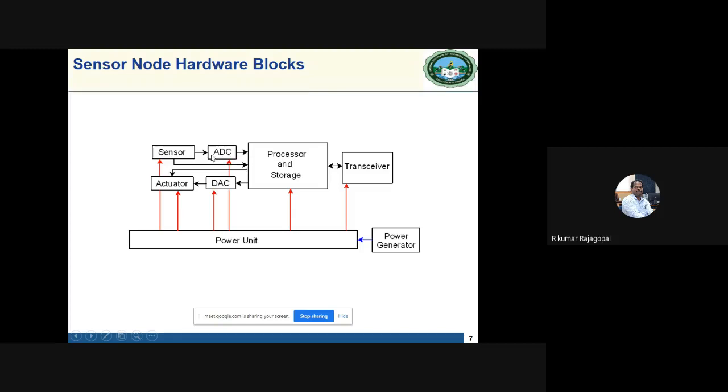If you are using ADCs or direct analog interfaces, we need at least one amplifier, signal mapping, filters, and the ADC. The ADC may be 8-bit, 10-bit or 16-bit resolution. So in the case of direct digital integration, we don't need any amplification, filters, or analog-to-digital conversion.